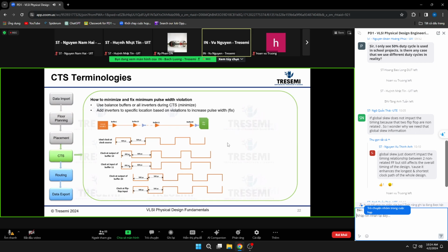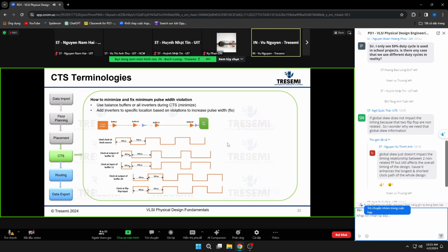To give you an example, if you have a subsystem that has a machine learning block, which is typically pretty large, you probably want to have a dedicated clock for that block by itself, and not share it with the bus interconnect that block is connected to. That's just one way to minimize the skew. So the answer is yes, at the SoC architecture we do architect the clock tree, partitioning the clock into multiple subsystems.